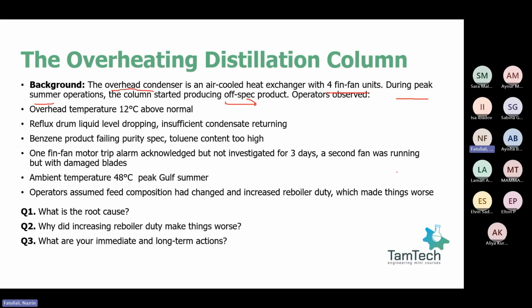Off-spec means that you have some specification from, for example, a vendor, that my oil has to be sulfate free or limited to, for example, 2 ppm sulfate, or the color should be like this, density should be like this, temperature should be in operating range, pressure. There are some variables for your product specification. If they are out of the range, it's called off-spec product.